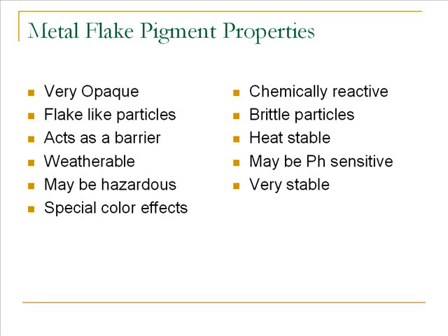Properties: very opaque, flake-like particles. They act as a barrier. Pretty good weatherability. There are some hazards involved with it. Special color effect, chemically reactive, brittle particles. So again, you want to be careful. You don't put too much energy into it to break them apart. Heat stable, and can be pH sensitive. So you've got to be careful what materials you put them into. And in general, very stable chemically. Here's another picture. There's a red.